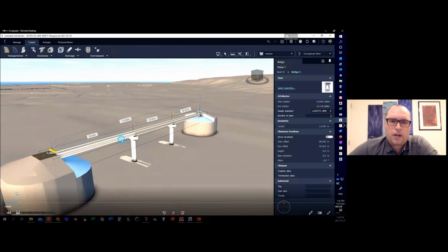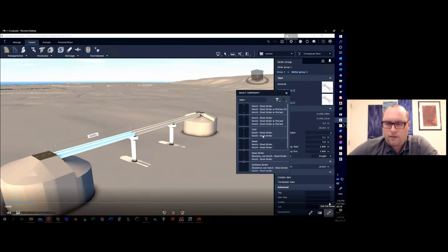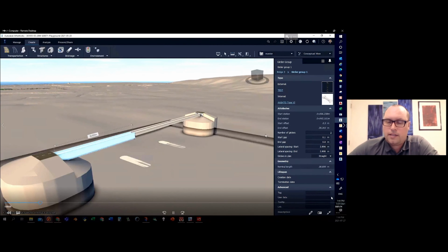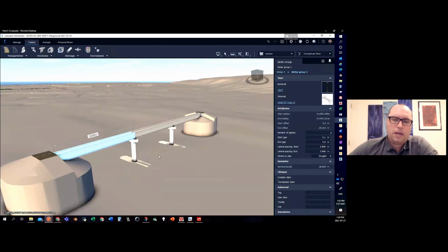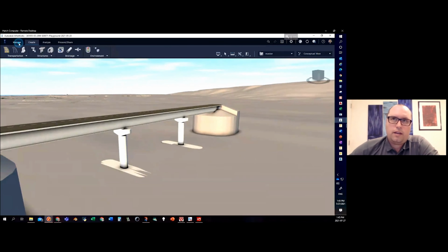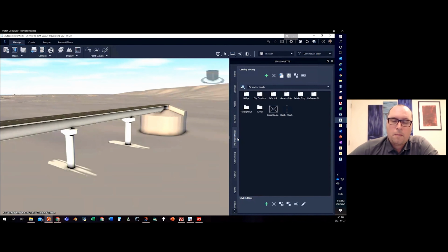So here's the video of me putting those components into InfraWorks. One thing is for the parts like cross braces where they're pinned onto a different component, they have to be a matched set. So as an example, say I have the parameter ABC123. Well, the girder has to have ABC123 so that the cross braces can have left girder ABC123. And so they have to go as a paired set.